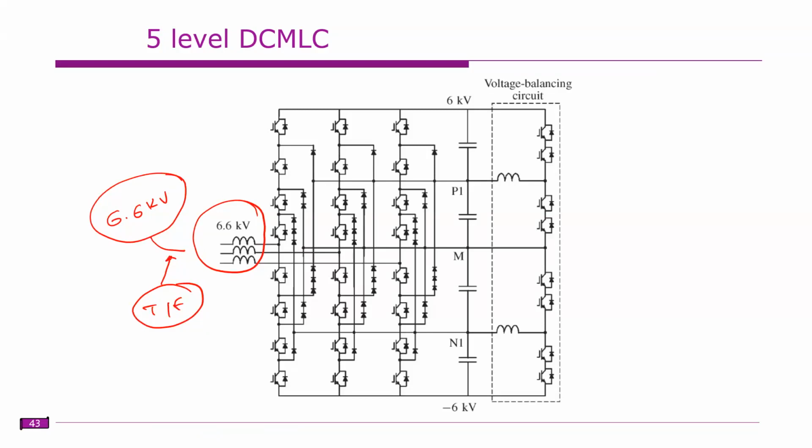The idea is, the grid has some voltage, for example a 32.62 kV grid. Earlier, what we had to do is use a lower voltage, maybe 2.3 kV, so the rating of the converter is 2.3 kV. Now with all these things, we can bring the converter to match the grid voltage levels, so we can connect directly without using a transformer.